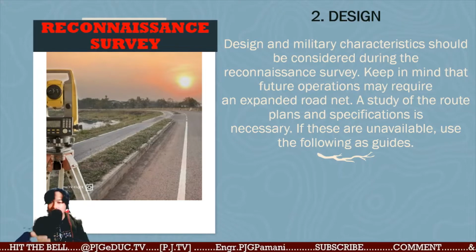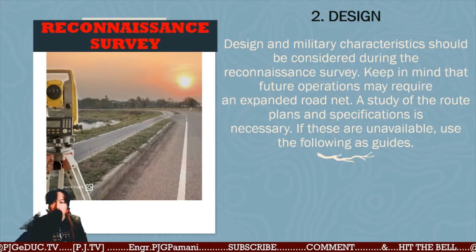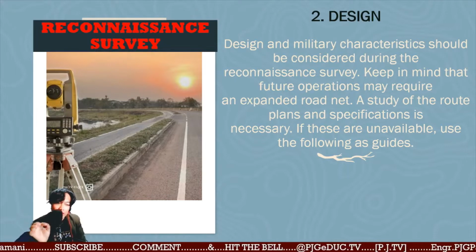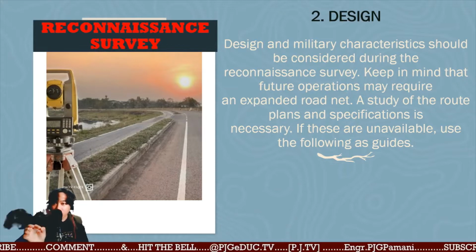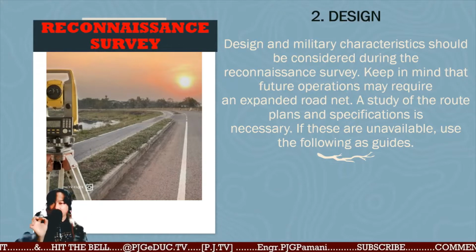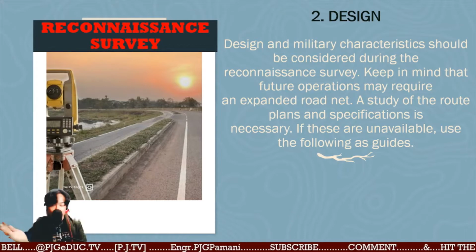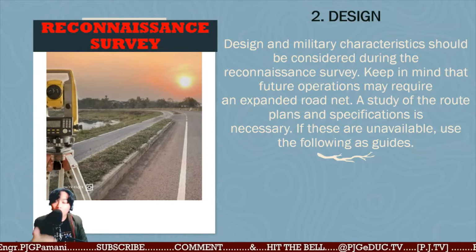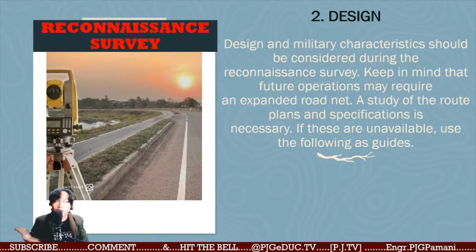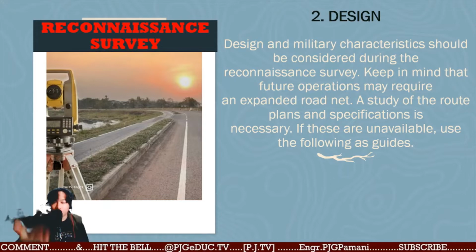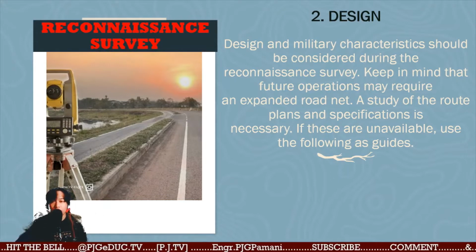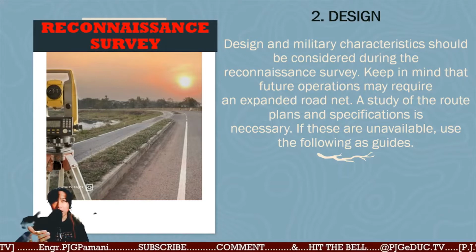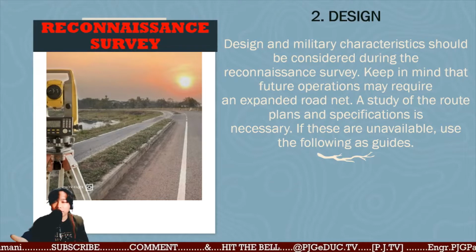During the design process, an engineer specializing in road construction always needs to consider that this particular road will have to expand at some point in the nearest possible future, by considering the volume of vehicles that will use this particular highway. So first up, in this first construction, we are going to provide two lanes. Those two lanes will accommodate around 1,500 vehicles per day.